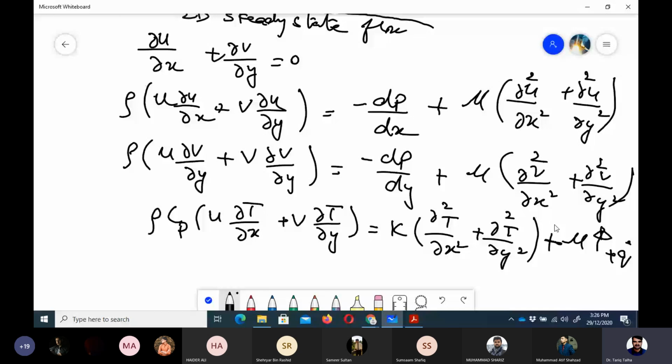due to friction. You can easily see that dissipation of energy when you rub your palms against each other. You feel some heat being generated. So that is frictional energy being converted into thermal energy, right? So in the fluid, due to the viscosity, some of the fluid energy is being converted into thermal energy. So that is the dissipation of energy.